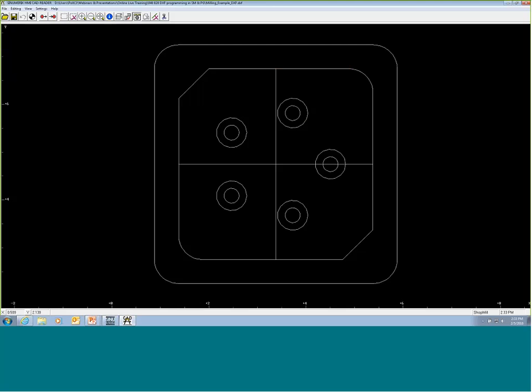So what we're going to do first is look at how I establish a new part 0. I can use my bullseye, or I can go to the editing function, come down, and look at the set 0. Both will give me the same options. So what I have here are some different scenarios as to how I can pick features. We do have an element center, and when they talk about element, they talk about any feature on a physical part. I can pick the start or the end point of an element. So if it's a straight line, which side of the line do I want?